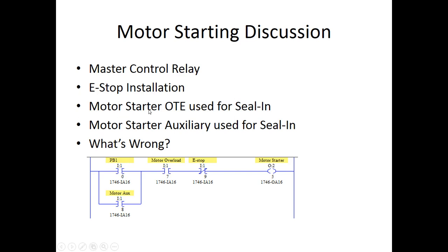We're going to explore using the motor starter for the seal-in circuit, okay? And then we're going to use the motor starter auxiliary for the seal-in, and we're going to take a look at using the overloads in a circuit. So if you take a look at this circuit right here, okay, let's figure out what is wrong.